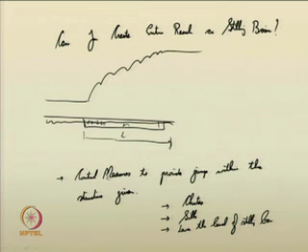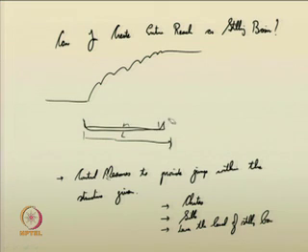See, if I just lower this portion like this, you will have something like this. This stilling basin will also provide the jump, but it can be economical, right. So, that way we can design stilling basins according to the need, and in an economical way.